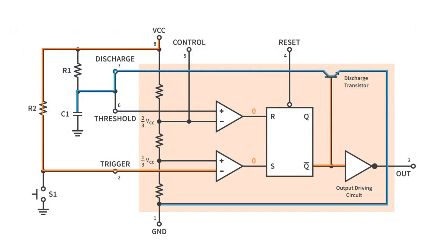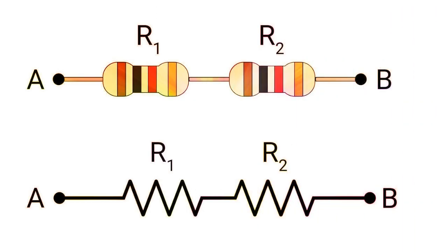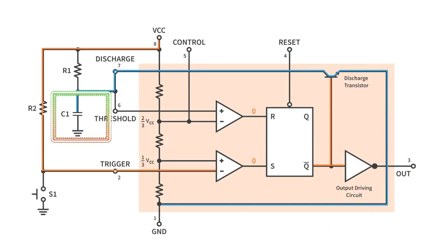If this time difference of 17 milliseconds, 500 to 517 milliseconds, is unacceptable, instead of one single timing resistor, two different value resistors could be connected together in series to adjust the pulse width to the exact desired value, or a different timing capacitor value chosen.